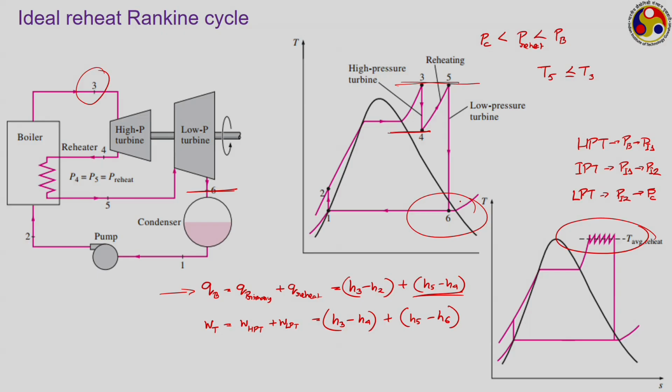In fact, because of reheating we may get some increase in the efficiency, we may get some reduction in the efficiency as well. And the change in efficiency with the adoption of reheating generally is not more than 1 or 2%, but the biggest gain is here. The turbine exit quality will be significantly higher compared to a single stage turbine expansion. Also, generally the heat that is produced in the boiler, if we are not using any reheating, a significant part of that heat produced because of the fuel combustion may get wasted. So, we are also able to make better utilization of our resources by the reheating.